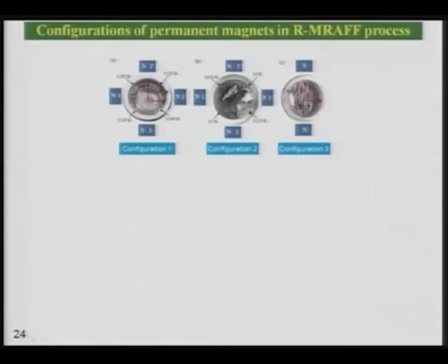In the second configuration, you can see the magnetic brush is formed and may be stronger than in case 1, but it is not uniformly distributed. There are certain pockets where there is no brush, and other pockets where a strong brush is formed. In the third case we tried with two magnets only, and again a similar problem was there: there are certain pockets where no brush is formed, and certain areas where a strong brush is formed, or continuous.